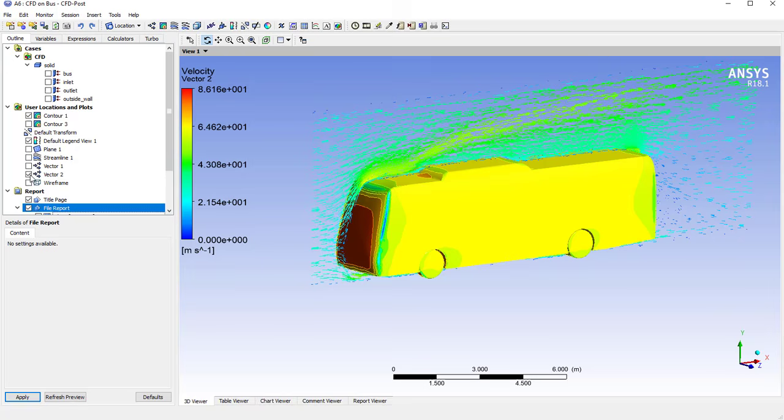And then after that we had gone through the process definition, name selections. Once that is done, in the general settings you can define the gravity and all, and then the unit system, and then define all the boundary conditions like inlet velocity and all, and then define the model. So the k epsilon model we had taken. Once that is done, whatever results you are looking for, you can just define the definitions for drag and drag coefficient, which I was looking for.